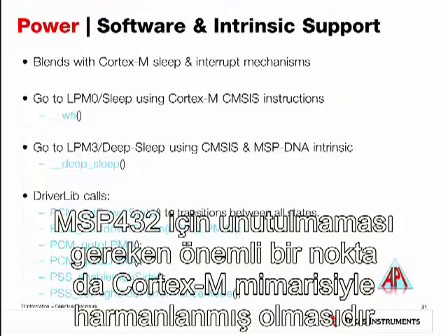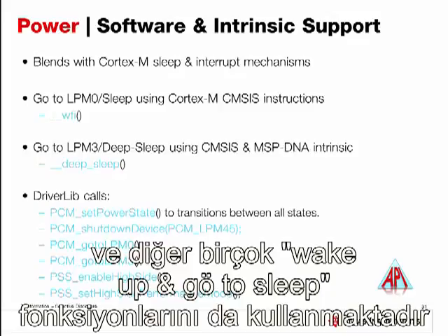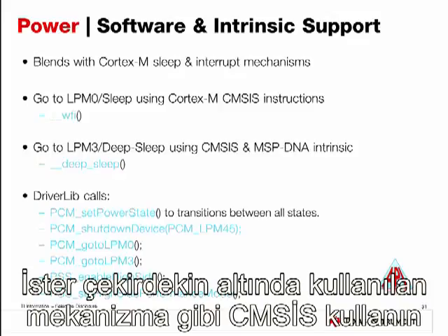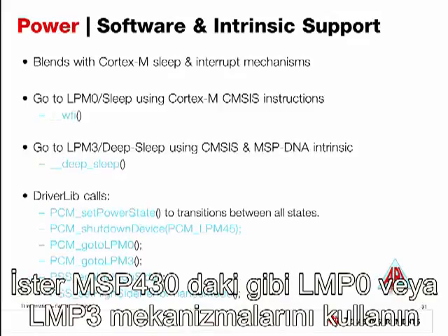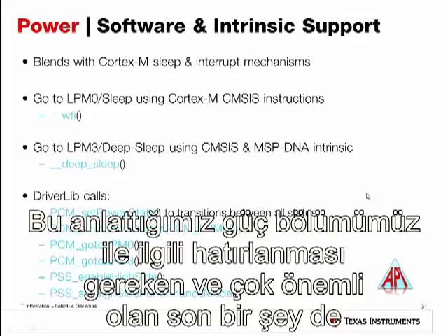A few things to remember: the MSP432 blends really well between MSP and the Cortex-M architectures, and it uses the same sleep and interrupt mechanisms to wake up and go to sleep. There are a number of ways that you can use to instruct the device to go to sleep or wake up. You can either use Cortex-M CMSIS instructions, such as __WFI. You can also use MSP430 intrinsic conventions, such as goto LPM0 or goto LPM3. In addition to the intrinsics, we also provide a set of driver library calls that will allow you to transition between states extremely easily.